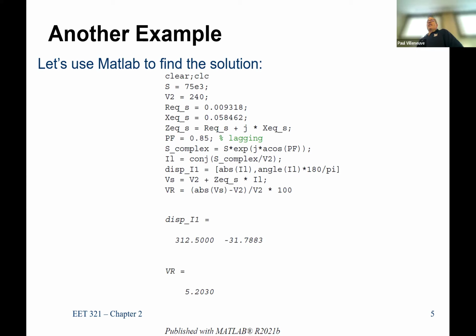Like if you look at the grid, they have surge arresters. And if the voltages go above maybe 10% of nominal, maybe 15%, they'll actually respond, because you get switching transients. But there are cases where if you drive something at more than 5%, you might have an overvoltage condition, or you might be pulling in too much current. Remember, if we just put a resistor on there, the voltage goes up, the current increases, and you could damage it because you're running it at higher than nominal voltage. So that's why you have a tolerance of typically around plus or minus 3%.